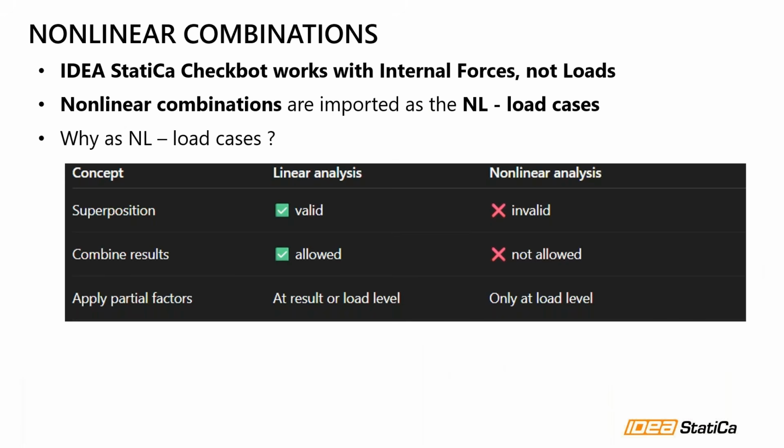If you are using a linear analysis, you can just superimpose the internal forces in the post-processing. That's a valid approach, that's legit. But if you are using the nonlinear simulation, this assumption is not valid at all. So this is the reason why we are exporting the single load cases that you added to the result classes. Also, the combining of the results, as I mentioned, is supported for linear analysis, but not for nonlinear analysis.